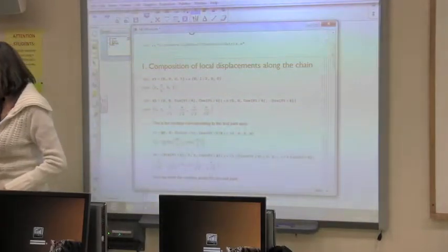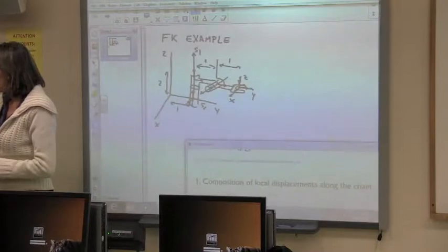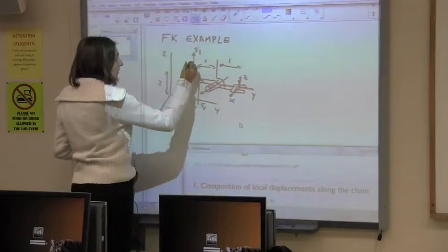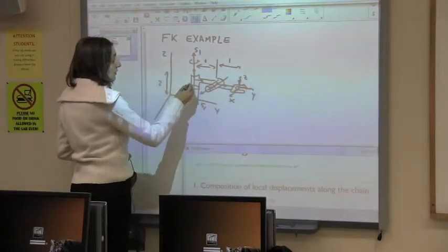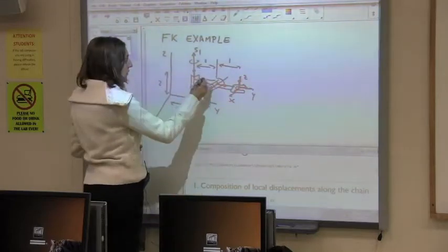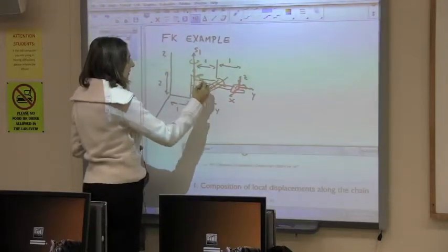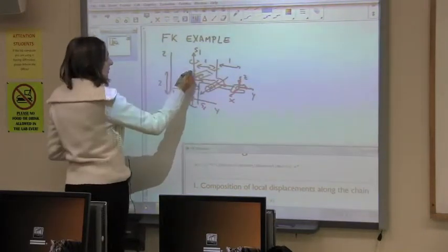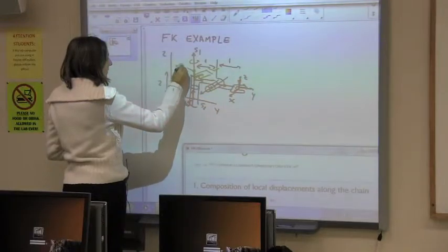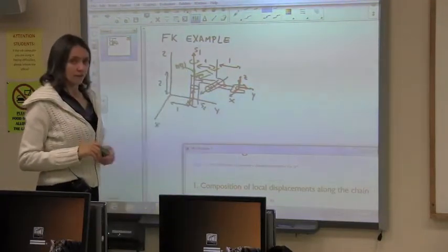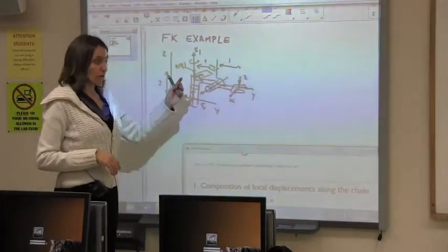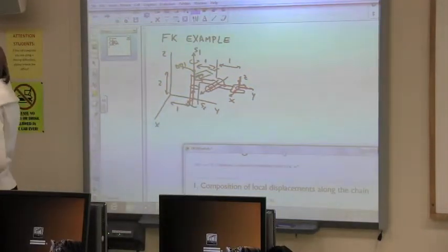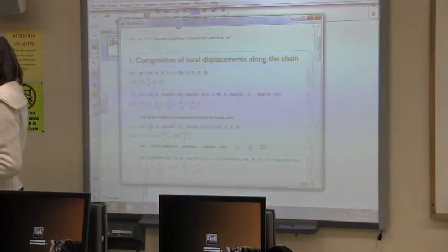So I'm going to show you. We are up to here. Okay, I'm going to show you here. So right at this point, once we have arrived here, now if this joint rotates, everything will rotate with it. So we add this rotation. Imagine the whole robot moving with it. So imagine we are going here, and the whole robot moving with it. Okay. So this will be our z of theta 1. Okay. Everything else doesn't move the configuration of the robot, only the joint motions. So there is where this z of theta 1 goes. We put it right after the z2.